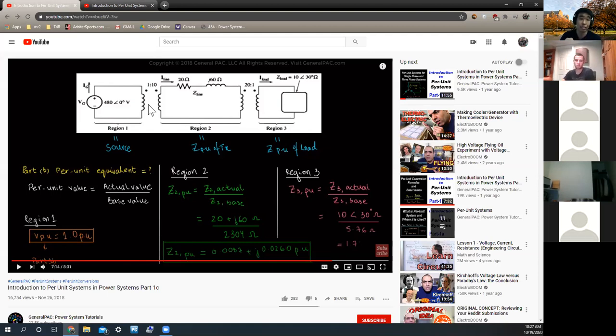Okay, because we're not going to be dealing with ideal transformers in most cases. When we do this, the resistance we often just ignore, but the reactance of transformers and generators is actually not that small. It's fairly significant if your line is not very long. If the line is not terribly long, the synchronous reactance of the generator and the reactance from the transformer contribute significantly. It's not an insignificant part of it, so we normally don't ignore it.